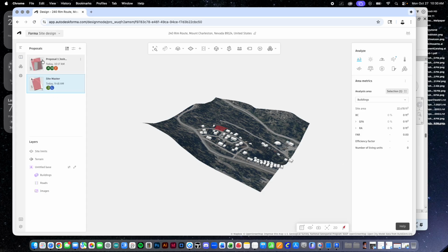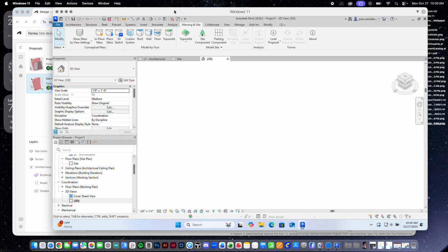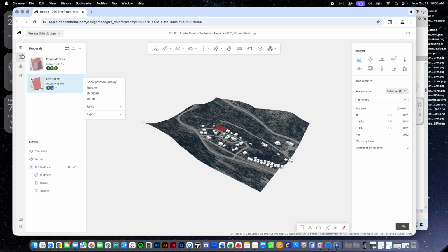But really quickly, just to differentiate, if you're not seeing all of this, you need to maybe re-log in, refresh your browser, right? And make sure that you have access to send the Revit add-in data. Now, if you don't have this stuff over in Revit, in the massing and site, where you have a little Forma section with load proposal, and you can update and manage and go back and forth, right? Then in Forma, you need to get the plugin in order to do that, right?